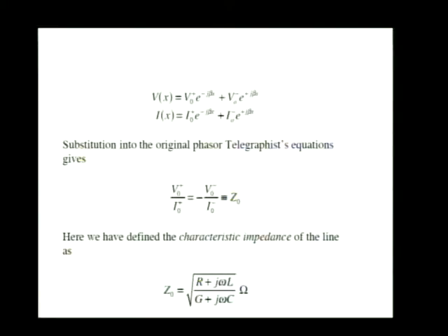Okay, you give a technician a 50 ohm transmission line and tell him, here's a 50 ohm transmission line. And the guy will scratch his head and say, 50 ohms, okay, what does that mean? Where do I measure the 50 ohms? Can I connect an ohm meter between the two ends of the transmission line and measure 50 ohms? No. Can I take an ohm meter and connect it between the outer conductor and the inner conductor at one end of a transmission line, like a coax line, and measure 50 ohms? No.